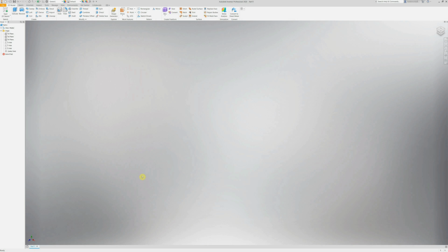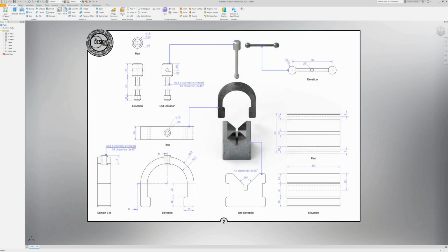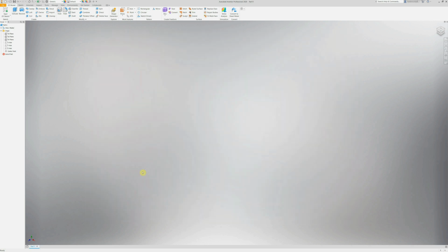So we're going to create the axle component, or the threaded component that goes through the shoe, the one that touches the handle. I really wish I'd named all the component pieces on the drawing now, but you'll see the one I'm talking about. Now, to do this, I can use any of the vertical planes. I can use the XY plane, which is looking from the front, or the YZ plane, which is looking on the end elevations. Because the component's cylindrical, it doesn't matter so much.